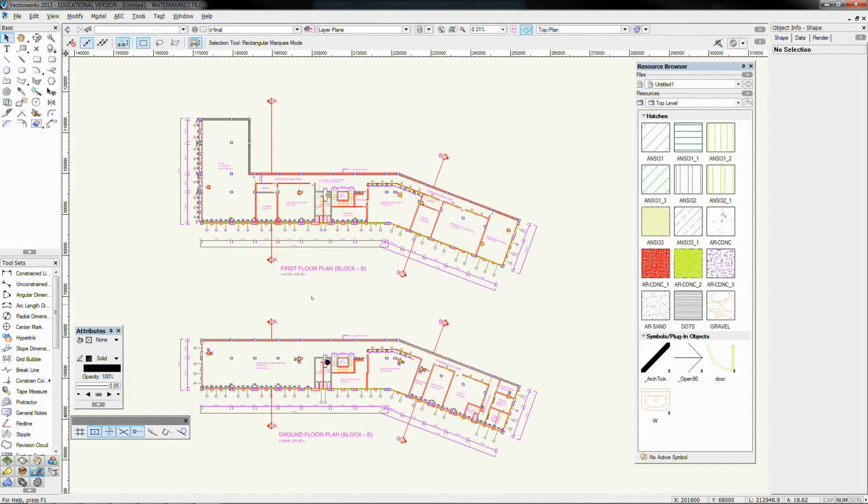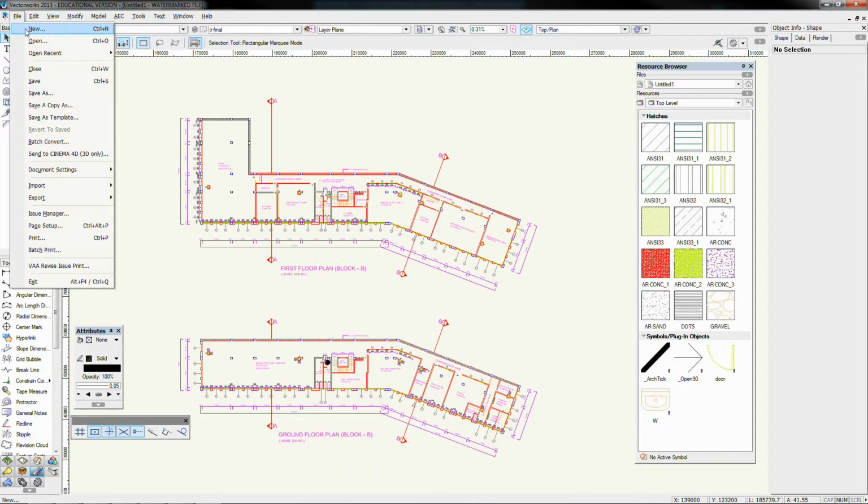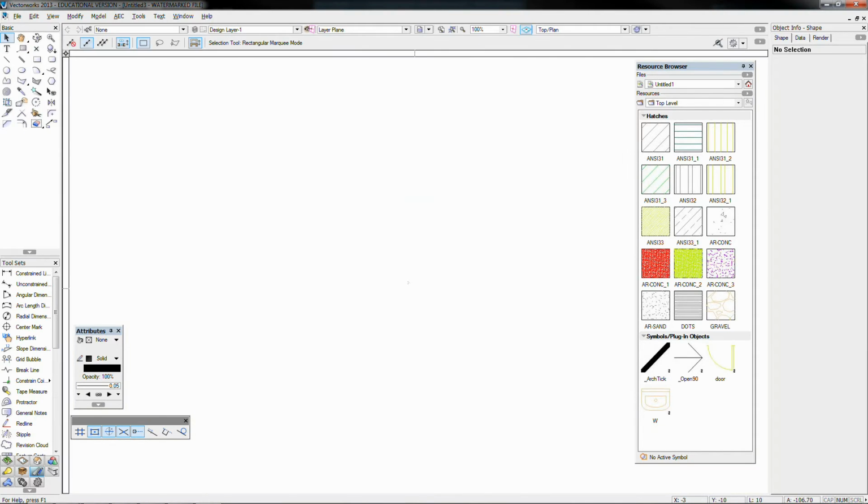So it's always important to check that the drawing that you're bringing in is scaled up to the right size, and sometimes you might have to get your scale ruler out, hold it against a PDF, or check it out, find out the venue drawing and figure out what needs to be scaled up or what needs to be scaled down. So I'm just going to start a new document straight out here, new blank document,